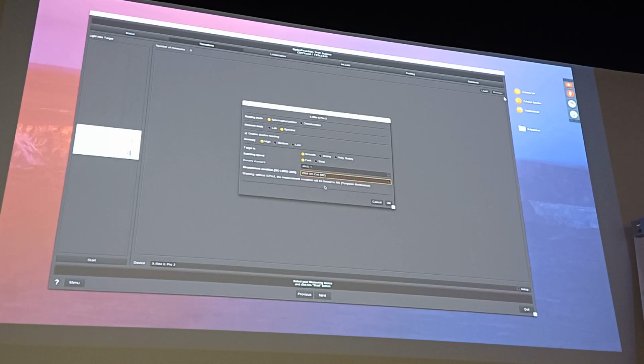The M2 is only for very specific cases. For instance, if you know that you will print for a very specific environment, like a museum or hospital, where there is not that much UV in the light, and you won't have any issue regarding optical brighteners. But usually this is almost not used. Usually you will choose between M0 or M1, and if you are not sure, go for M0.